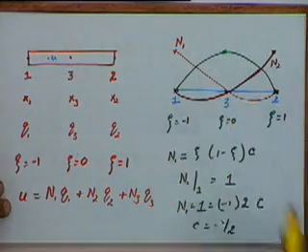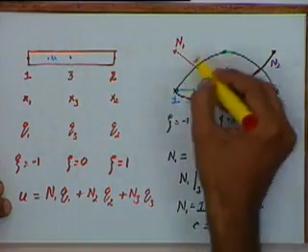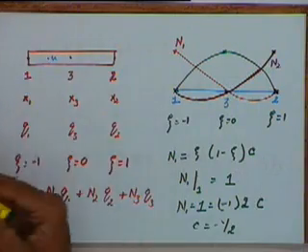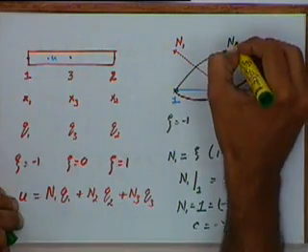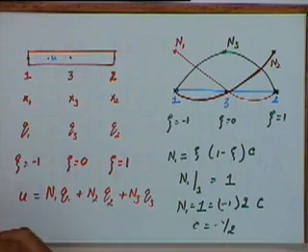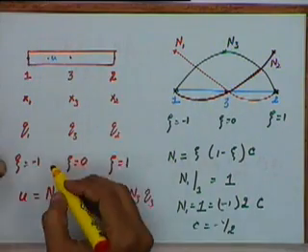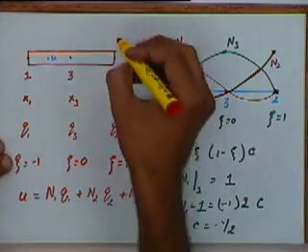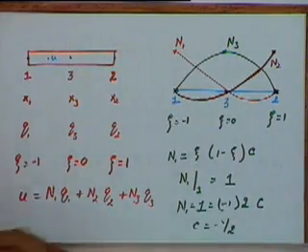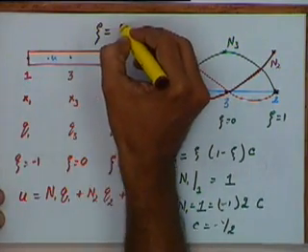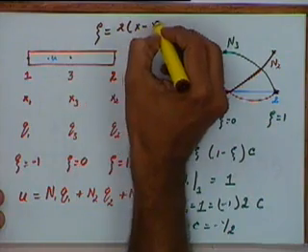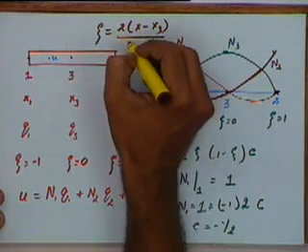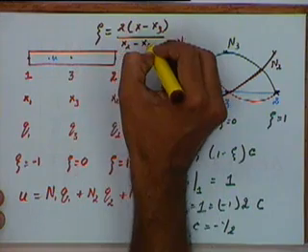If you look up this formulation, we found out expressions for N1, N2 and N3. This is N3 in terms of zeta, and zeta in terms of x. Zeta in terms of x is given by zeta will be equal to 2 times x minus x3 divided by x2 minus x1.